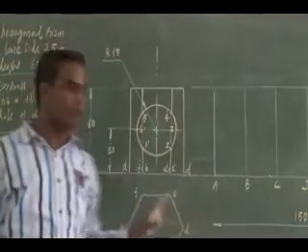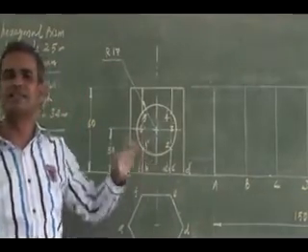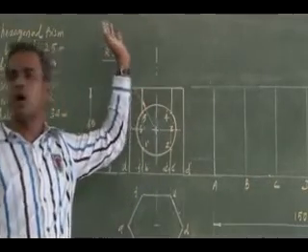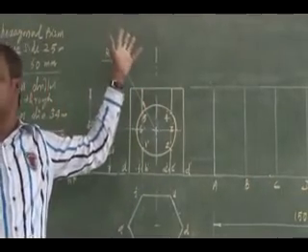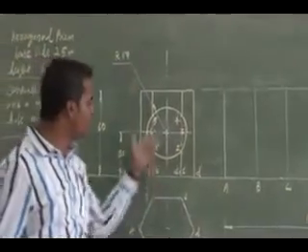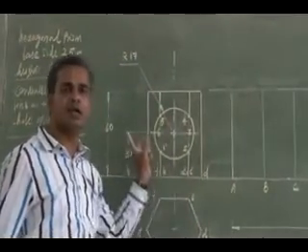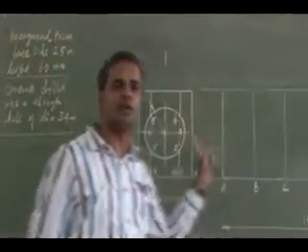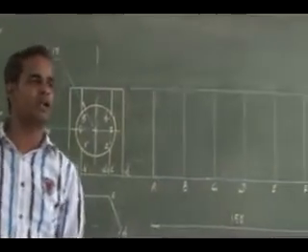Is it clear? If I open it, I can see 2 holes in my development. Since the hole is drilled all the way through, it comes through behind the face. So on the visible faces I will have a circle, and on the hidden faces I will have a circle. I have to mark the cutting points, totally 10 locations.